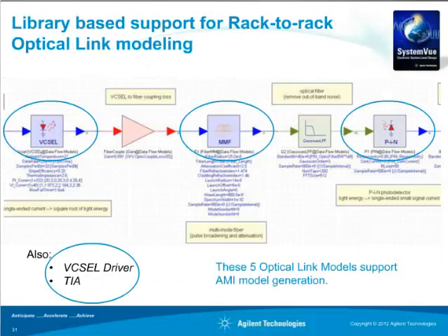Specifically for optical links, we provided 5 models inside the library that you can use, parameterized behavioral models for 5 key elements that are used in an optical link. Our targeting for these first 5 models was really what we call rack-to-rack, so it's a multi-mode fiber-type environment. So there's a VCSEL driver, a VCSEL model, the multi-mode fiber itself, a pin model, and a transimpedance amplifier. Those are the 5 models that we've included specifically to support an optical link as part of the channel.